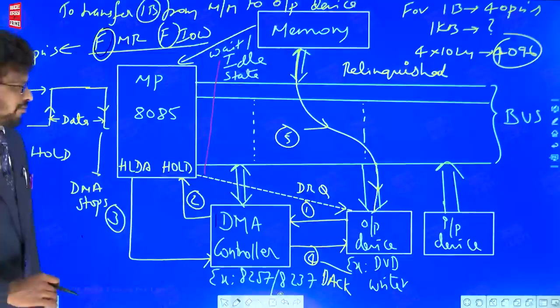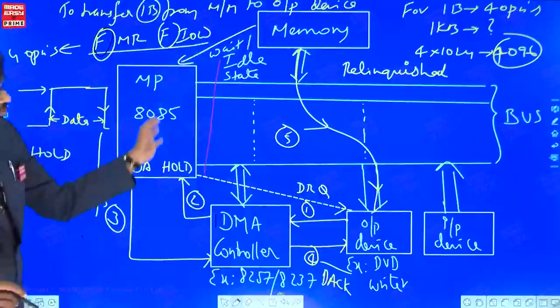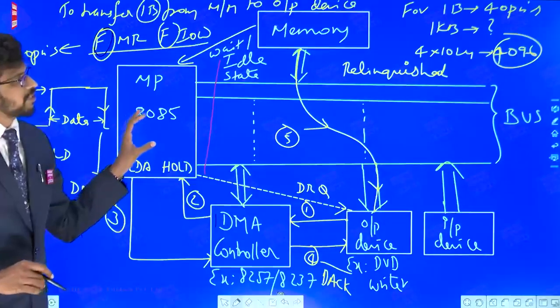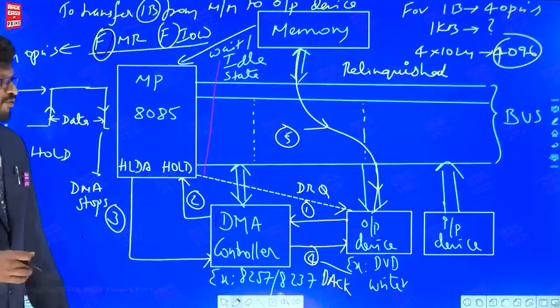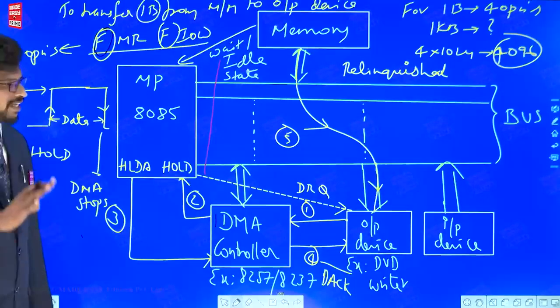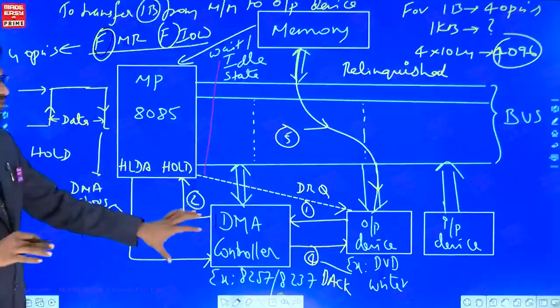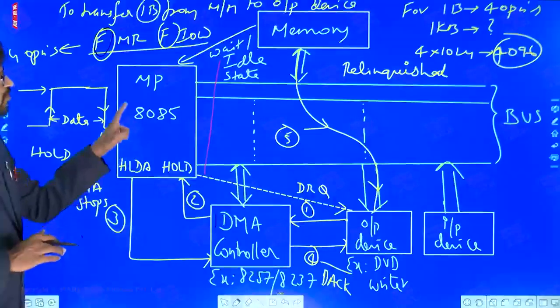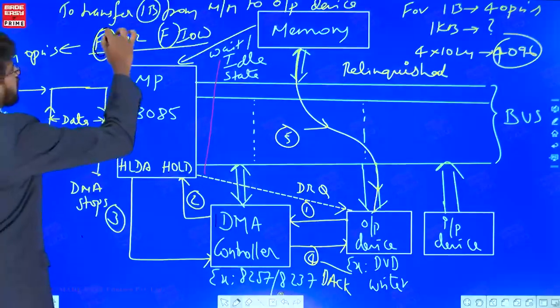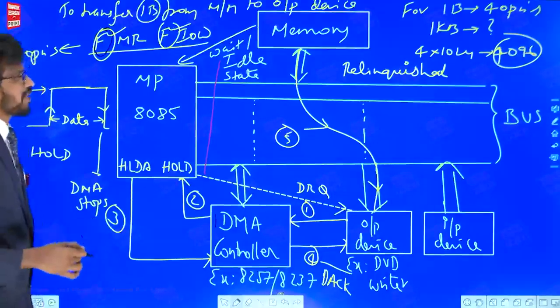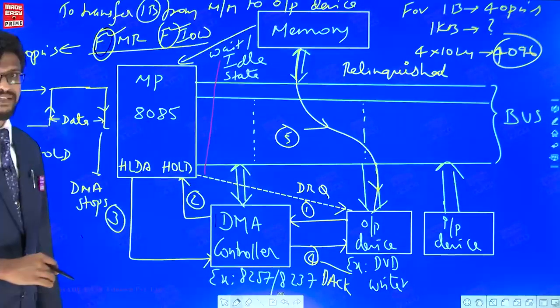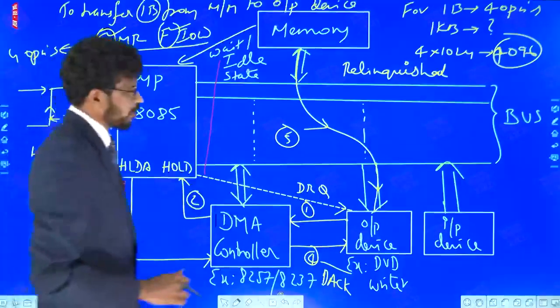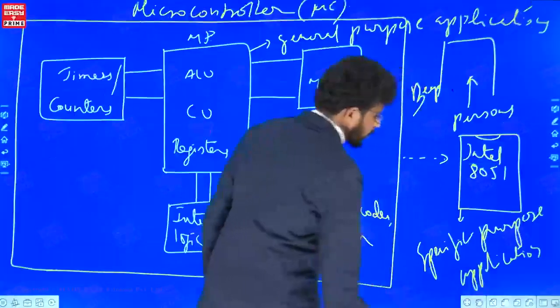Now, my question is, through processor also there is some mediator, through DMA also there is some mediator. Then what is the use of it? Here, DMA is meant for fast transfer of data. With respect to processor, what was the disadvantage? You are using the fetch number of times, memory access is more, time is wasted. But how is DMA advantage as compared to the processor? See, DMA controller is also something like one of the processor. So how it happens, let us see now.